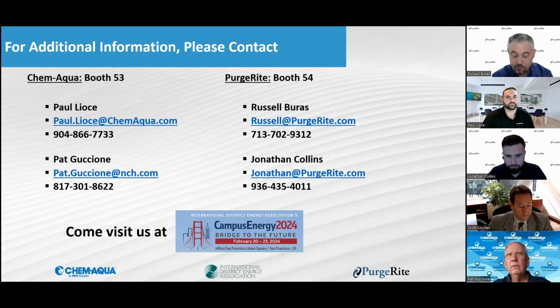There'll be usually a couple components in there. One may actually get down into the details of what the engineer has specified for flushing velocities and durations. And there's also a chemical treatment section typically in division 23.